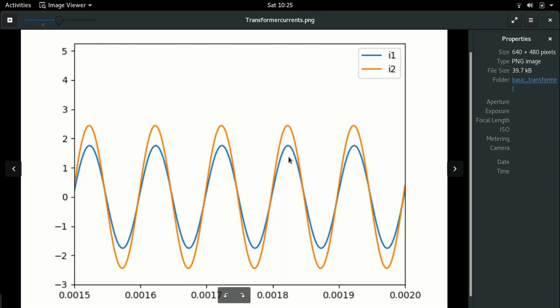The reason for that is the magnetizing current, right? This is what we've already seen. And if you want to verify that, by all means, make the resistance on the secondary very large so that this secondary current is almost zero, and verify how much is the magnetizing current. That is an exercise I will leave for you.